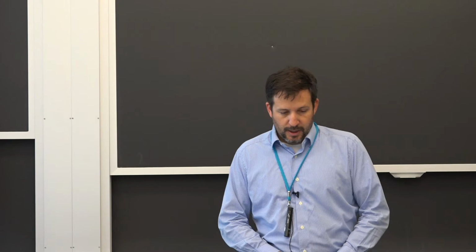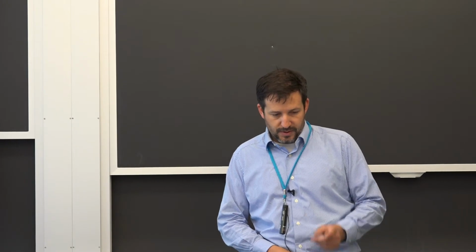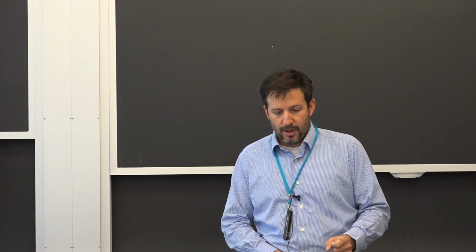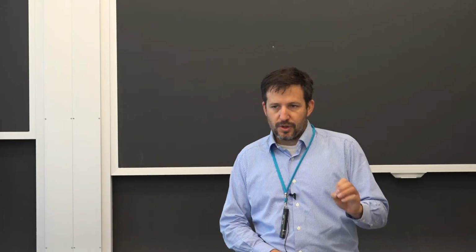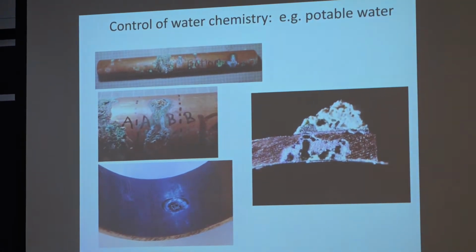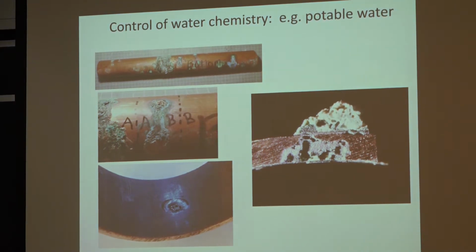I mentioned these examples of pitting corrosion on copper, and I believe I was brief, but I essentially emphasized that the issue of very localized pitting, which could look like a drilled hole, is specific to the metals that have a protective layer. So we see it on aluminum, we see it on copper, we see it on stainless steel.